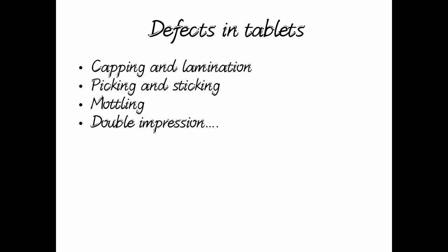to prevent such damages or defects like picking and sticking, as large as possible letters should be made in font size, okay, particularly the punch with small diameters, right? Moreover, if you plate the faces of the punch with chromium, that will also produce a smooth and an adherent face, so that will also prevent picking and sticking.